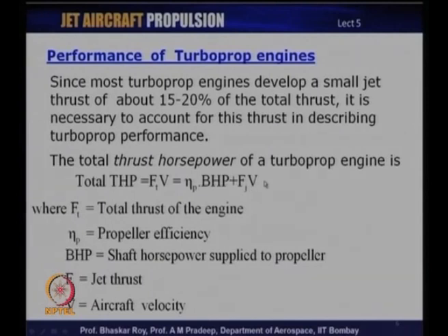So, two of them together make up the total power of this engine, and quite often they are expressed in terms of power rather than in thrust. One could do it the other way around, but this is basically a power driven machine, and hence most people would like to categorize turboprop performance in terms of horsepower or kilowatts rather than directly in terms of thrust in kilonewtons.